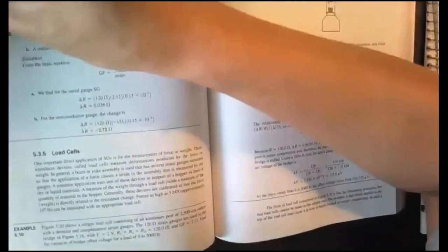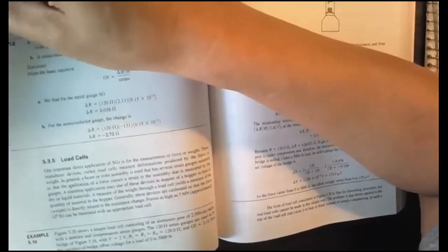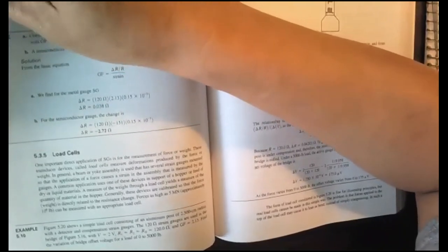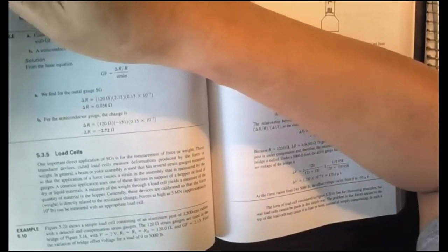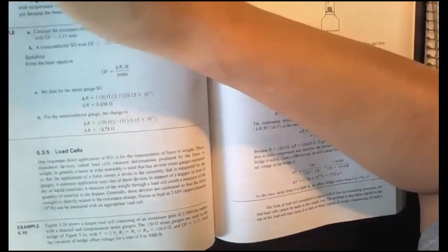The temperature sensor I demoed last week is one of those examples. It's 10 millivolts per degree, so the output is extremely easy for consumers. But that temperature sensor is a semiconductor. Again, just like the semiconductor strain gauge, it's nonlinear. But no problem, we can make that linear, and the output is perfectly linear.